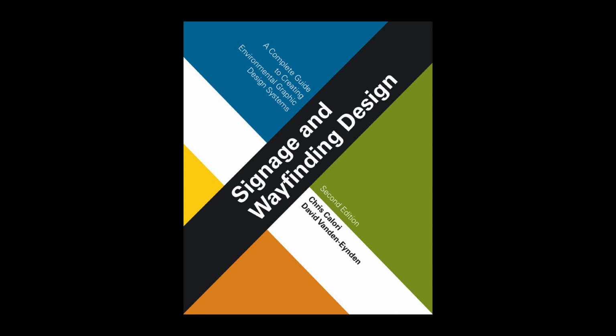Verdigris, a green or greenish-blue coating, such as that on the Statue of Liberty, is a common patina, as is a dark brown patina. Anodizing is a process by which the oxide layer that naturally forms on the surface of aluminum is thickened by an electrochemical process, forming a very hard, integral, almost glass-like surface coating.